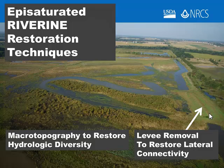This is one of the primary functions of riverine wetlands, that dynamic flood, for a whole host of reasons. So that restores the lateral connectivity of the flood hydrograph. In the interior of the wetland, the planners have elected to do some excavations of ponded surface water features, again what we call macro topography. The flood hydrograph receded long ago, but we still have large areas of residual ponding left over.